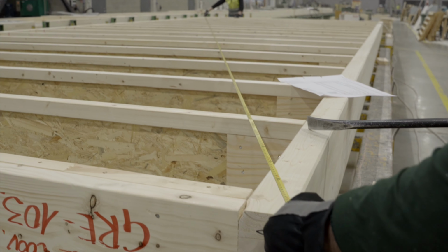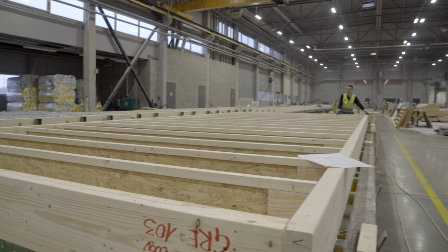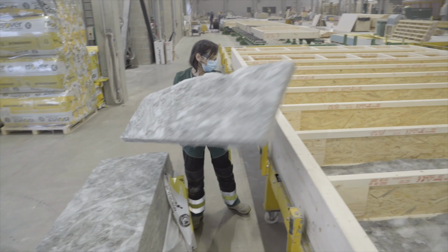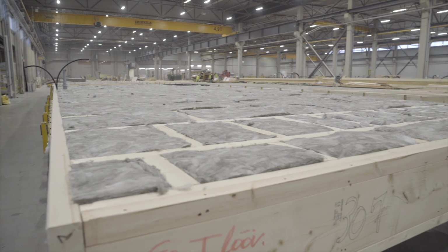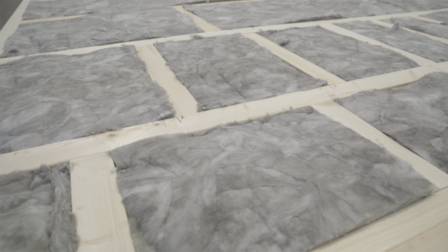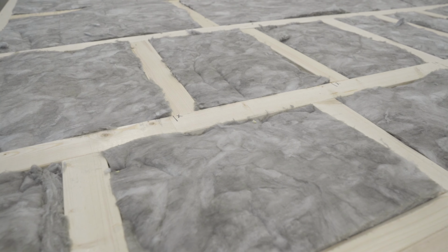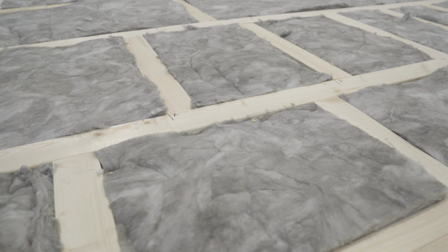Floor insulation begins with checking the dimensions and flatness between the beams. This means that before insulation, it is necessary to ensure that the structure meets the specified dimensions. The insulation between the beams must fill the gaps evenly and tightly, without any voids, creases, or folds. If the insulation consists of multiple layers, the joints between the layers should not align, but should be offset by at least 100 millimeters. A common mistake is to press the insulation down at the edges, causing it to sag. In such cases, the insulation should be slightly pressed in the middle and the edges pulled up to the same height as the beams.